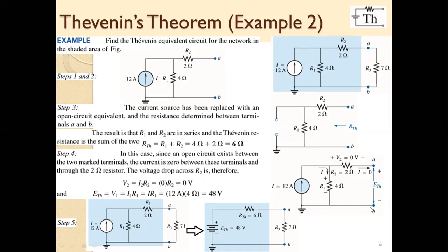So now the voltage from this point to this point would be what? The voltage over here plus the voltage over here, but here it is 0 volts. So it would be just the value of voltage in R1. Why not in R2? Because the voltage in R2 would be 0. So the situation is very easy. Here you will find the voltage with the help of Ohm's law, that is V equals IR. The I value is this one. All the current is flowing in this way, and the R value is given. So V equals IR equals what?